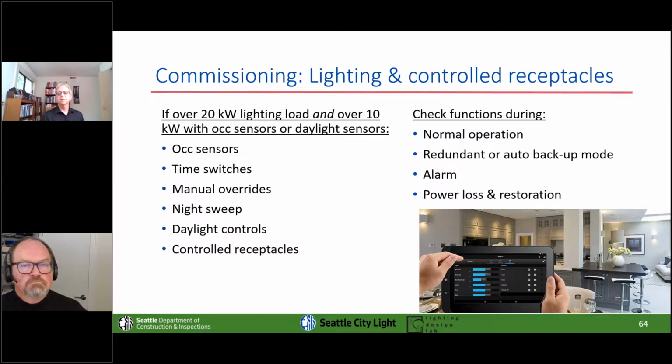I think it's probably hard to find very many solar water heating systems that are more than a decade old. So that's my prejudice: put PV on the roof, put a good heat pump water heating system down below. Oh, and the other thing is that there are 4 months of the year where we get 70% of our solar input, and you can only heat up so much water, and then you're done, and then you're just dumping additional capacity.